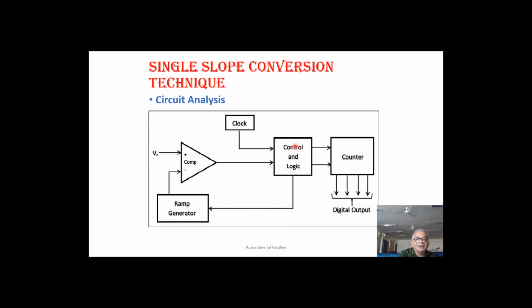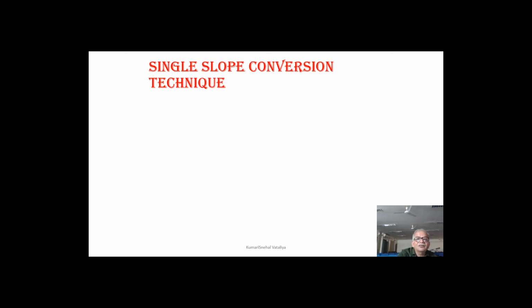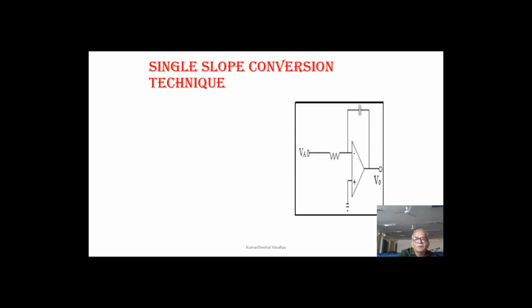And then this digital number is applied to a ramp generator. The ramp generator is an RC ramp generator using R and C. Ramp means inclined plane, so you get a slope instead of steps. Now you get a slope, smoothened steps, and then that is applied to the comparator as an input. So this is integration, meaning from steps you are making it smooth. Now this additional circuit, the ramp generator, will take time because it uses resistance and capacitance, and charging and discharging of them will take certain time.